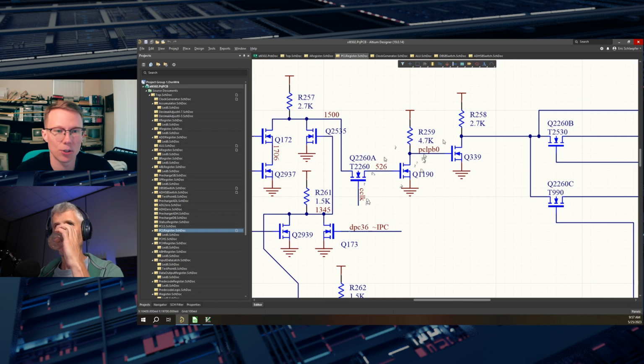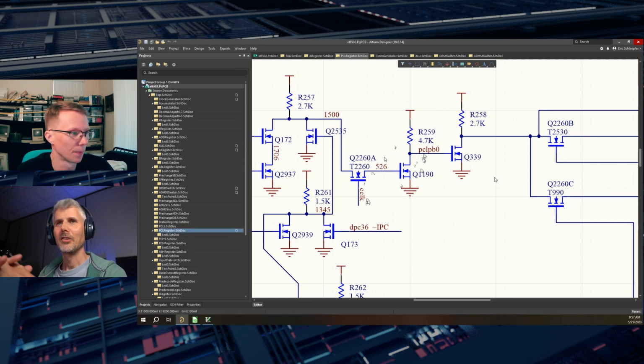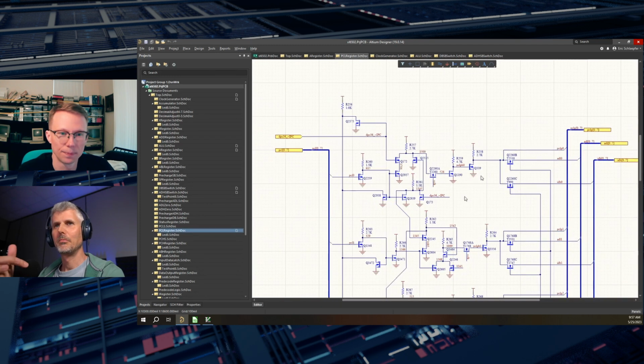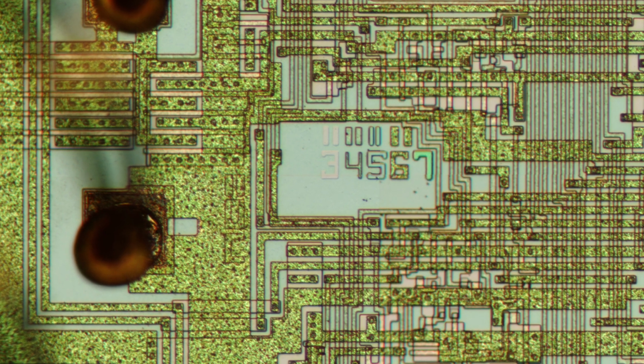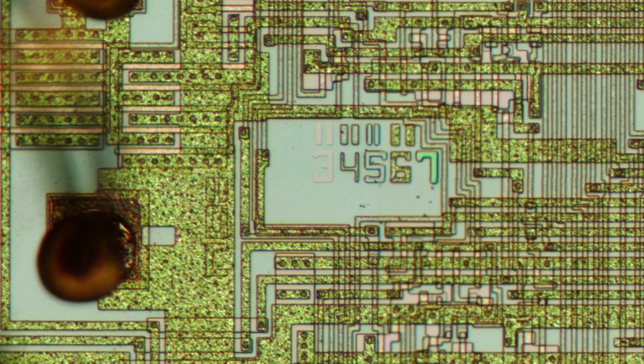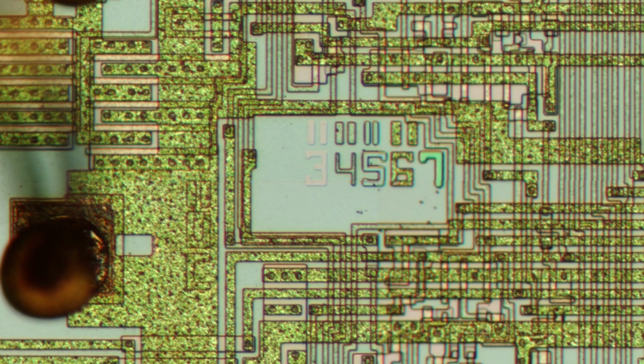That's a dynamic latch. So a regular latch is completely stable indefinitely in either a 1 or a 0 state, but a dynamic latch will slowly change from a 1 to a 0 as that gate charge drains away. Yeah, nice explanation. And I guess, related to the design is that the designers were thinking we're designing for a specific process. Like, one of the great pictures shown in that reverse engineering was the layers. It's like 8 layers, I think they were using. 7 layers. So very early, 7 layers.